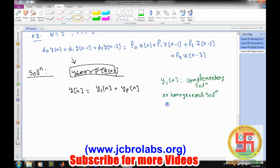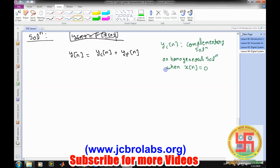It is calculated by putting x of n equal to 0. That means it could also be referred to as the natural response of the system, because we said y of n was the response of the system. So if we put x of n equal to 0, that means there is no input to the system. Even then, if we are getting some output, that is known as the natural response of the system.